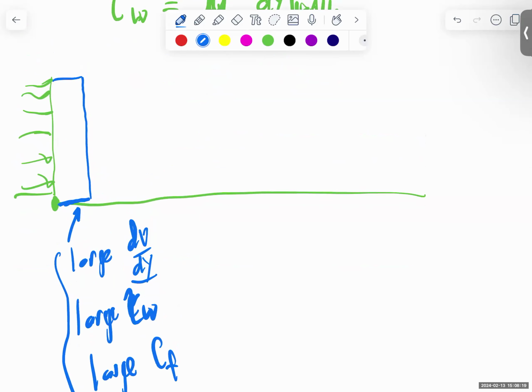So that is near the wall. By the time we get down here and things have relaxed, we went through the whole drawing earlier, so I won't redraw it, but things have kind of relaxed in space. The boundary layer is thicker like this. And now we have the slope. Think about this slope here. This is y, and this is u. So du dy is the inverse of that slope.